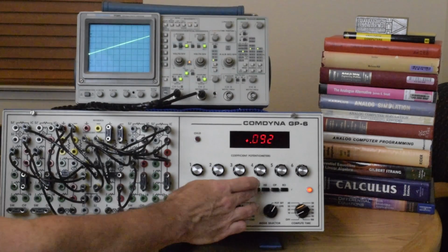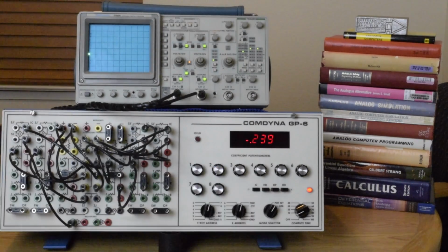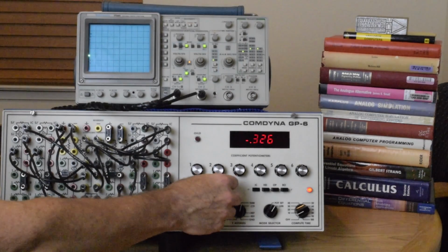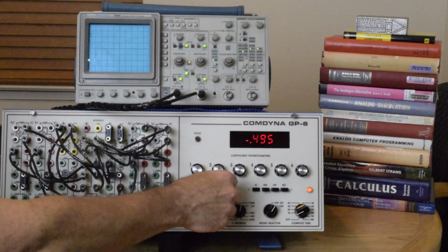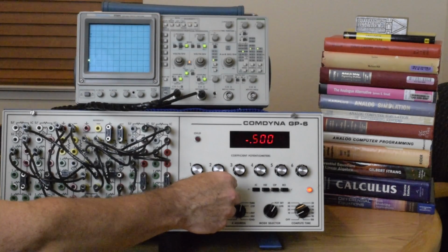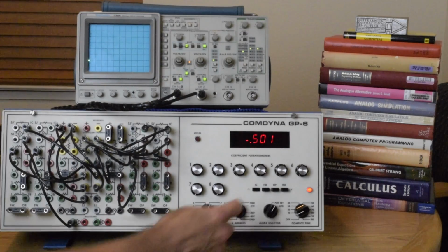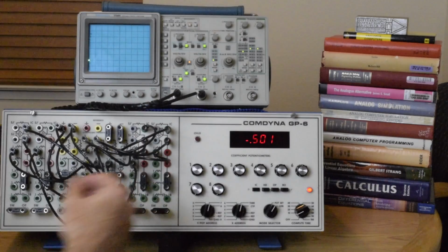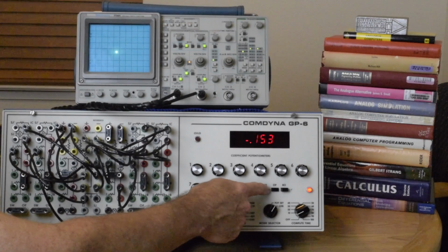But the normal operation mode might be considered just the operate mode, where we initiate the analog computer to its initial condition, and that's actually adjustable, as we saw earlier, by potentiometer 8, because it's plugged into the initial conditions. As we talked about in this very basic differential equation, that would be considered the constant of integration. Then when we run in operate mode, that runs it in a very slow mode so we can actually observe the problem as it moves across.